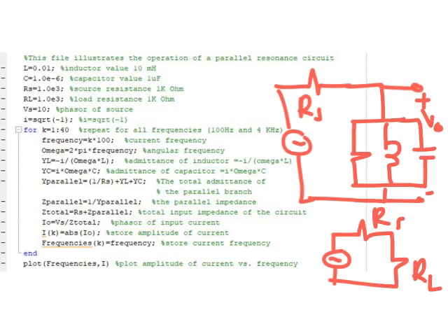Remember, when you put two impedances in parallel, the modulus of the net impedance is weaker than any one of the individual impedances, exactly like resistances. So at resonance, these two will not be there. Then the impedance of this branch will peak, and the current going through the circuit, which is V output divided by RS plus Z, will reach a minimum value, since the total Z is at its maximum.